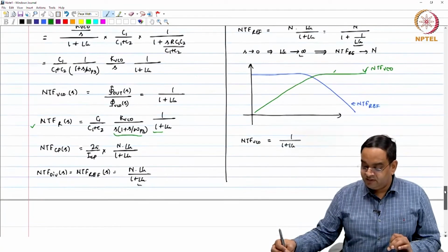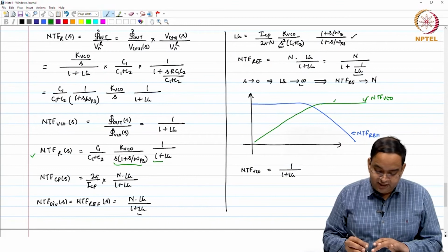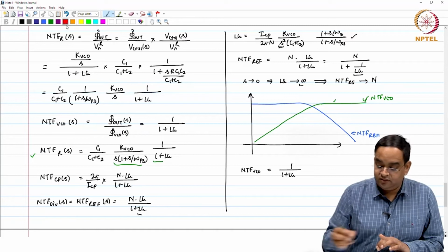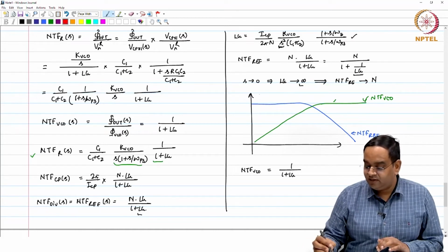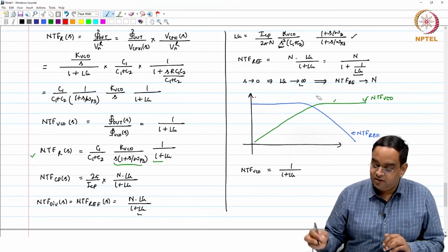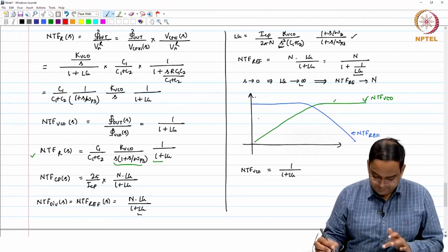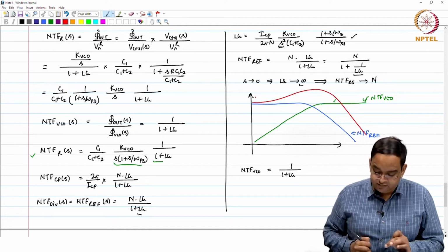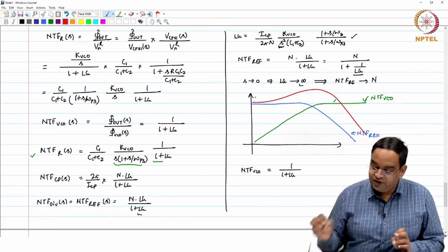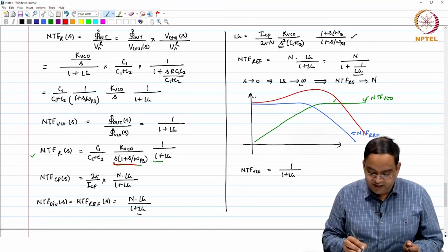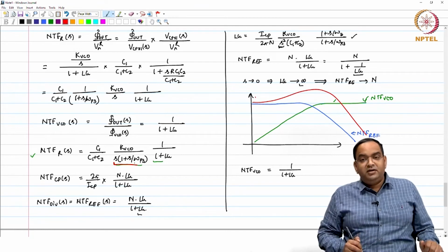So, if that is the case, your high pass transfer function is getting multiplied by a low pass transfer function, which, depending on where the poles and zeros are, may be something like this. So, overall, what you may find for your resistor transfer function may look something like a band pass transfer function, because at high frequency the low pass transfer function effect, which is S square, is going to take it down.